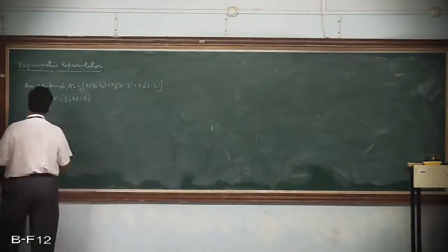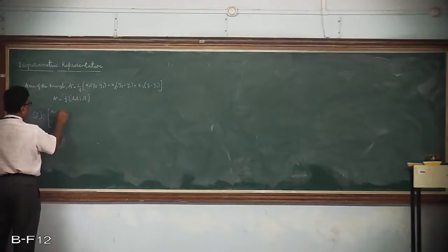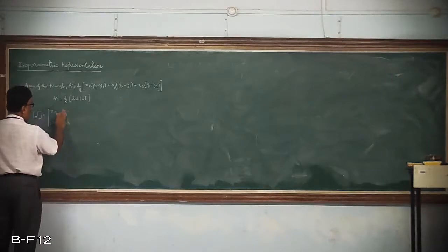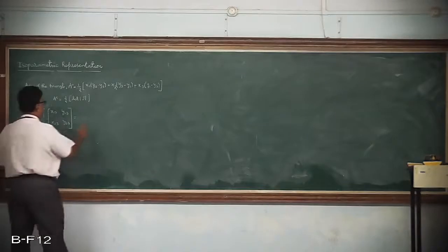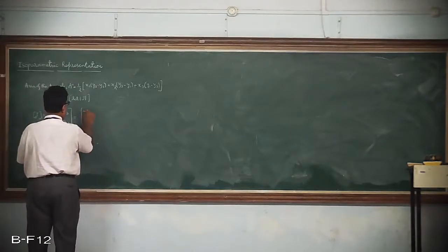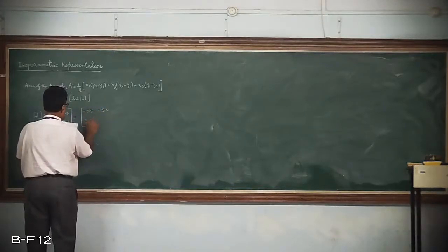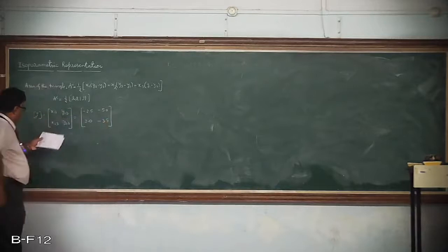So if I write the Jacobian, what will that be? Tell me. The Jacobian matrix we had taken there was x13, y13, x23, y23. Since you already know those values from the earlier problem on the triangle, tell me how much it is. x13 was minus 2.5, y13 was minus 5, x23 was 3, and y23 was minus 3.5. This was the Jacobian matrix.